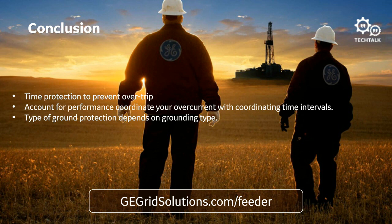So the question is, could you provide an example to calculate negative sequence, phase, or ground pickup values? What I would say there is, ground pickup values you should do in a similar way to how you've done your phase pickup values. For phase pickup, you're basically going to calculate your maximum 3-phase current, and then determine how far into the power system you want it to reach for a phase fault.